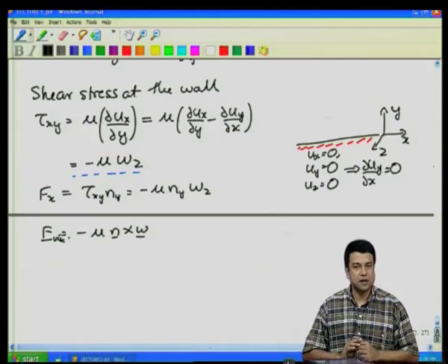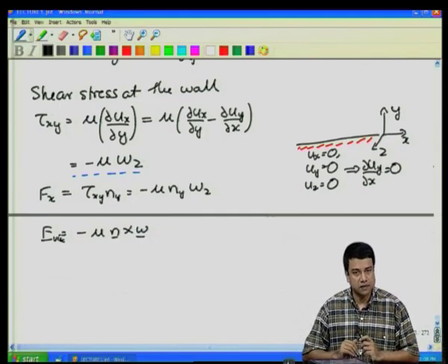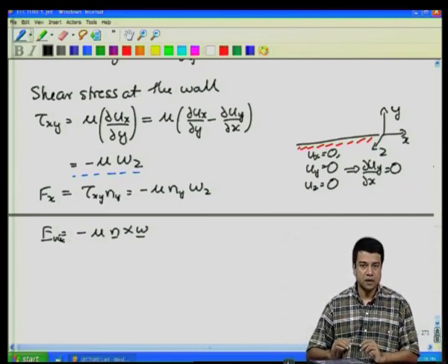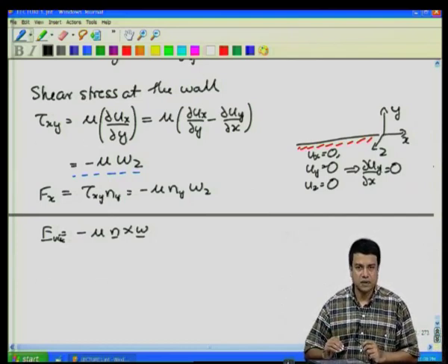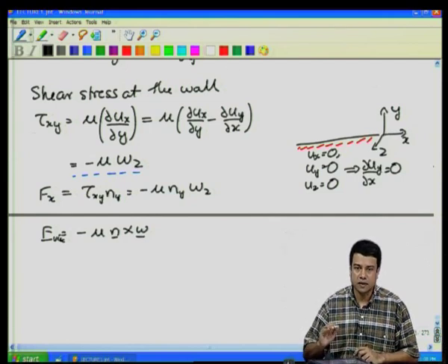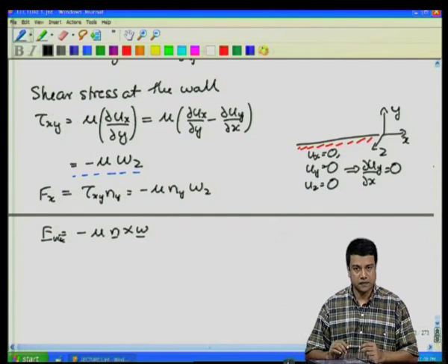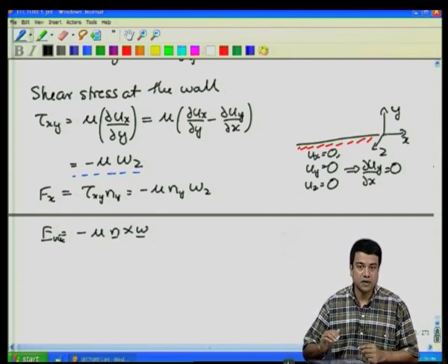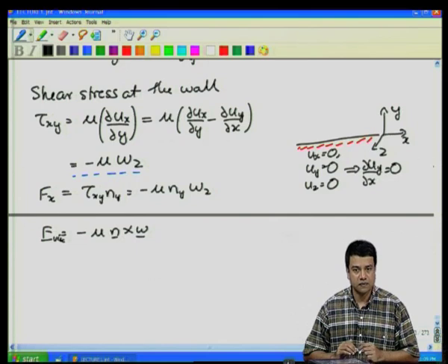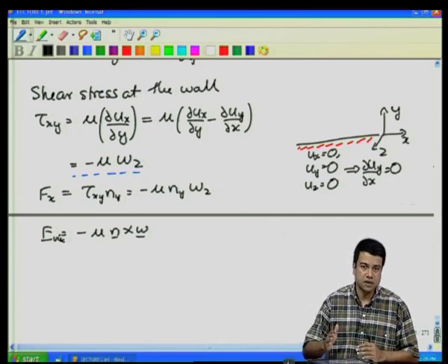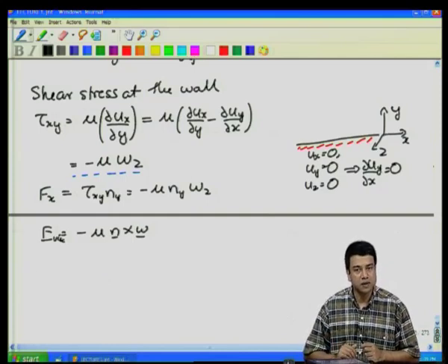Okay. So, this f vector is the viscous force. This basically tells us that the value of the vorticity at the surface itself is equal to the tangential viscous force divided by the viscosity. So, at the surface itself, the vorticity has a fixed value that is determined by the shear stress that is exerted at the surface. Okay. Similar to, for example, if I were doing a heat transfer problem, I would be able to fix the temperature at the surface. Okay. The temperature would have a finite value at the surface, and that it would change as you go within the fluid in agreement with the conservation equation, which contains the convective and the diffusive term.